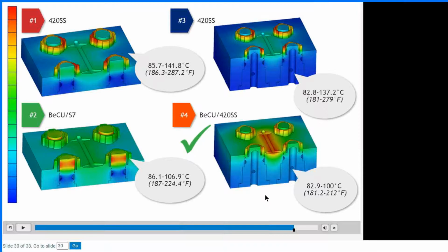So what I'm trying to tell you here is, number one, when you look at saving and optimizing quality, trying to optimize the quality and save cycle time, it starts with the part design. The part design needs to be optimized to cool uniformly. Then you give it to the mold designer who needs to mimic this behavior by laying out the water lines and tool steel selection correctly. And only then you have a mold that will function properly and gives you a low cycle time and high quality and therefore greater profits. Okay, that is very, very important.